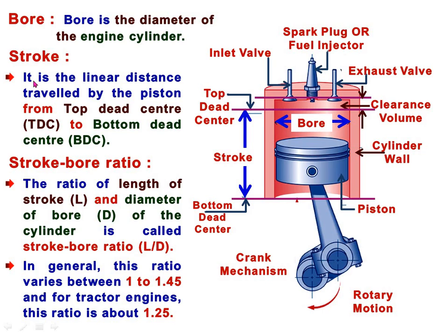Now stroke, or we can say length of the stroke. It is the linear distance traveled by the piston from top dead center to the bottom dead center. See, during the suction stroke, the piston travels from top dead center to the bottom dead center. So this linear distance from top dead center to bottom dead center is called the stroke.